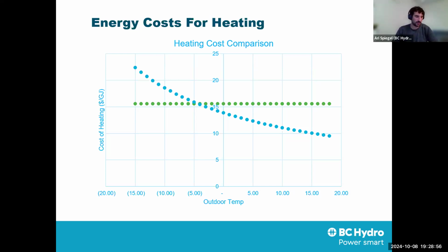The reason why we don't see a lot of them, at least in the province, because primarily when we're talking about Lower Mainland, air source can provide a lot of heating. Ground source is just expensive. You have to dig up your backyard. You're going to have to lay a bunch of lines in the backyard, probably down 6 feet or more below frost line. And it just becomes a costly measure.